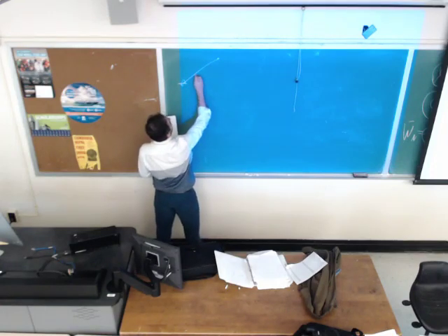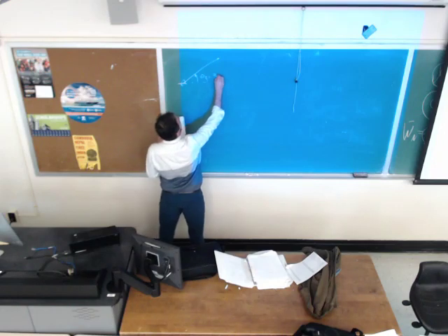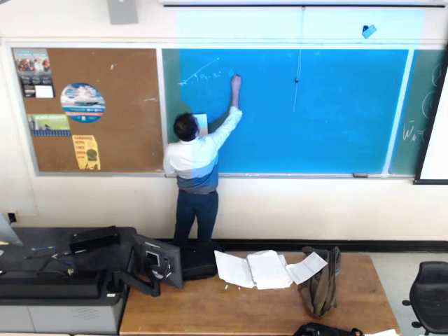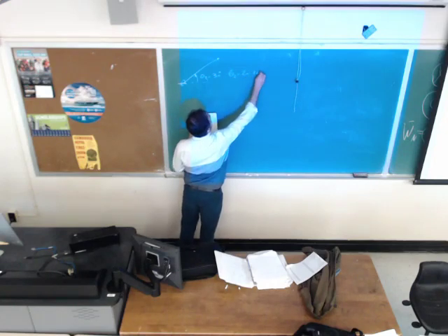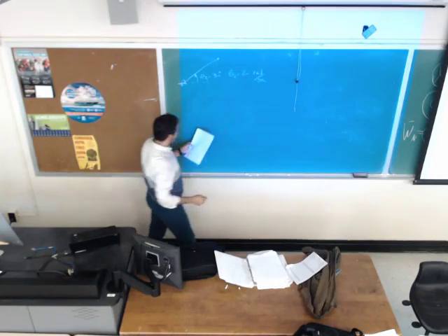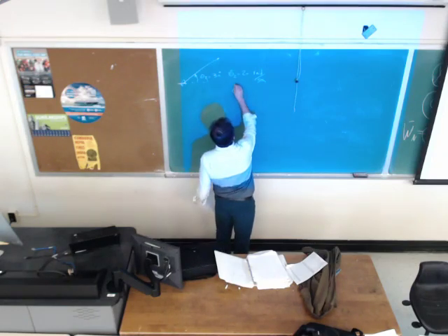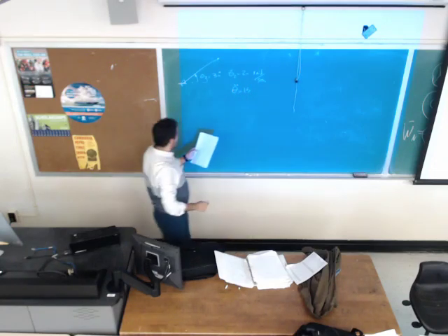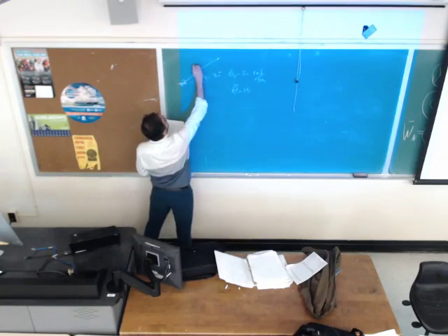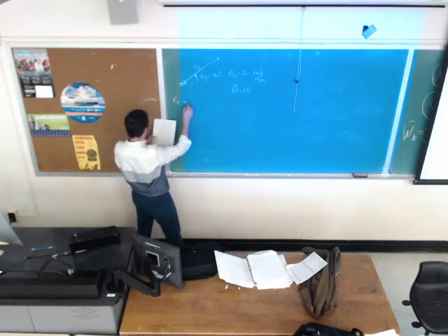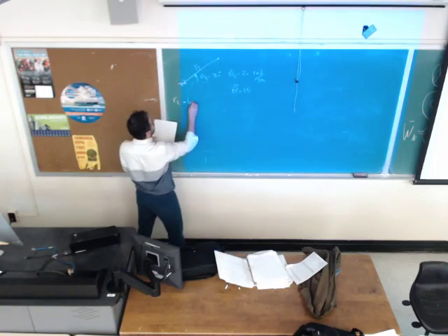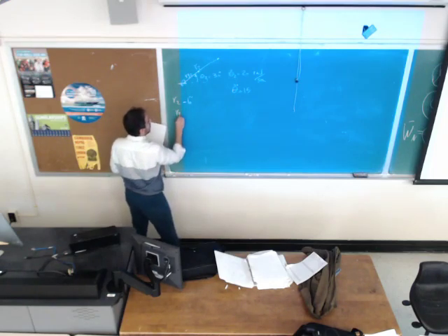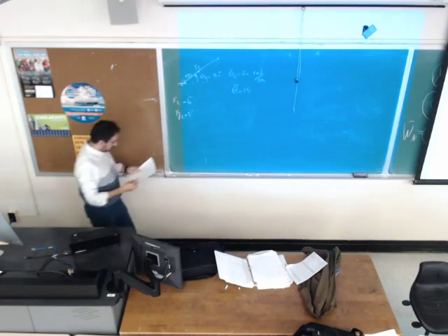So suppose for this one, theta 2 is 30 degrees and theta dot 2 is 20 radians per second, and the angular acceleration for the input link is 15. This is R2. R2 is 10 inch. And RG2 is going to be at the middle, so it's going to be 5 inch.